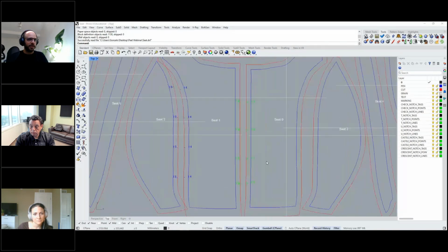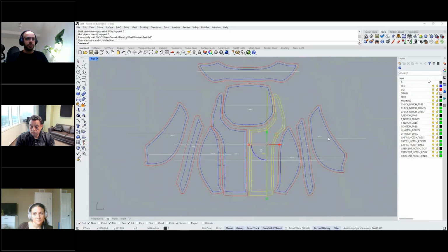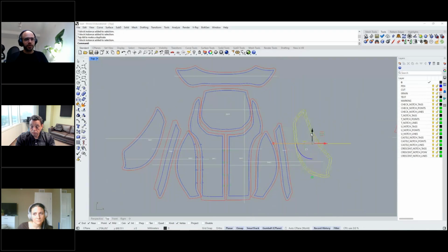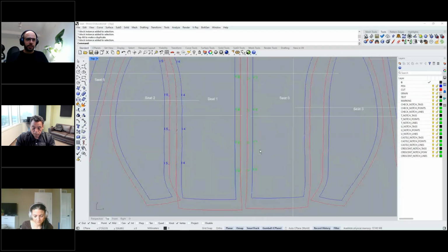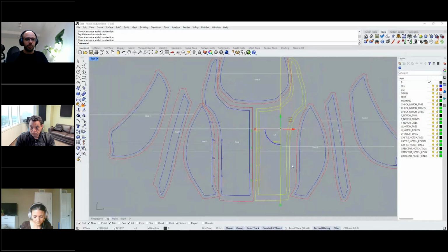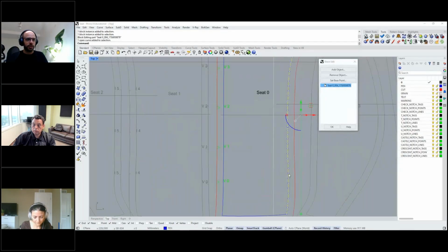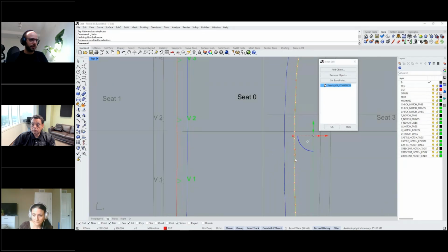All the tags in our pieces. Each one of the pieces is going to be a CAD block in this case, which means that it will basically group all the features that it has in it together. And this makes it compatible with any nesting engine that you may have. If you need to edit this CAD block or the geometry for any kind of reason, this is just simply a vector file. So if you, for example, open this up with any 2D CAD viewer, in this case in Rhino, I can double click at the geometry and this will show me the boundaries, and everything is just simply a vector polyline because of the profile that I chose.